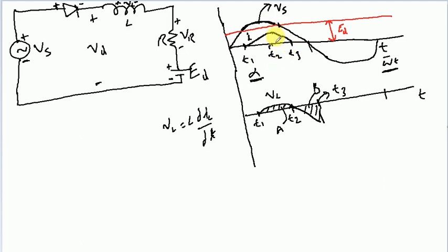So it all depends on the relationship of these two. One interesting equation: if you want to determine in theoretical numbers the point at which this diode will become forward biased, let us label this angle as alpha. This is the starting point at which the source voltage becomes more positive than the DC voltage across this source. So we can equate these two equations.